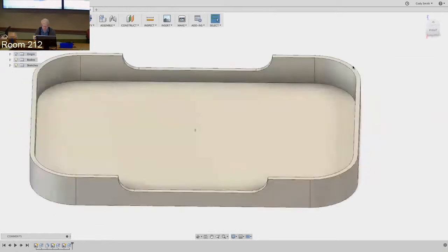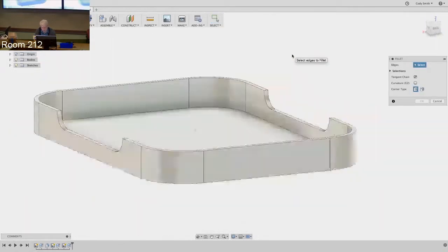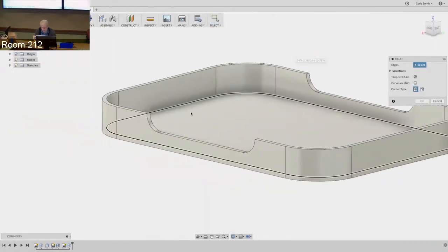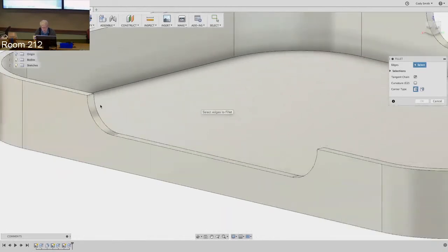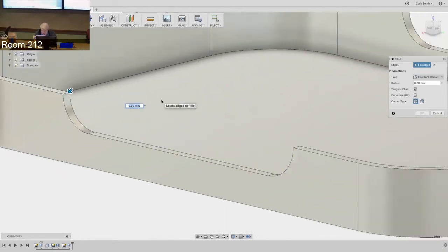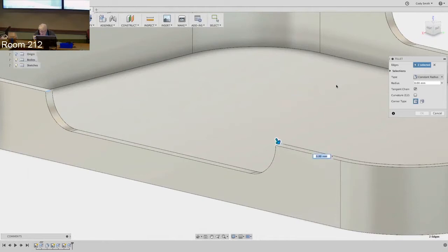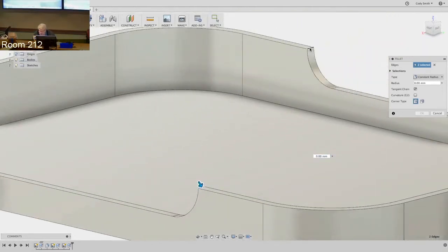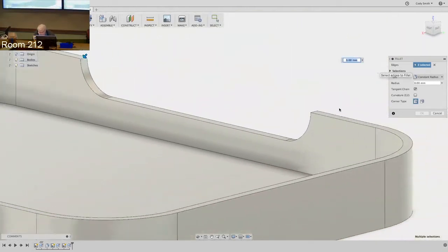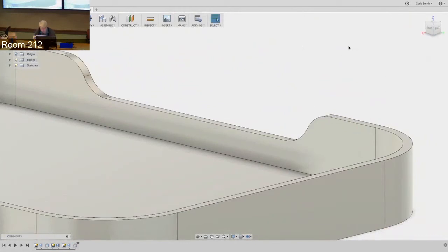And there we go. And then finally, I'll fillet those little edges we created just because I don't like to leave sharp edges in parts if I can avoid it. That's just a human factor thing. This isn't a particular sharp material, but let's say this is aluminum, that would be a sharp edge and people can get cut on that. So we'll do 3.5 here as well.